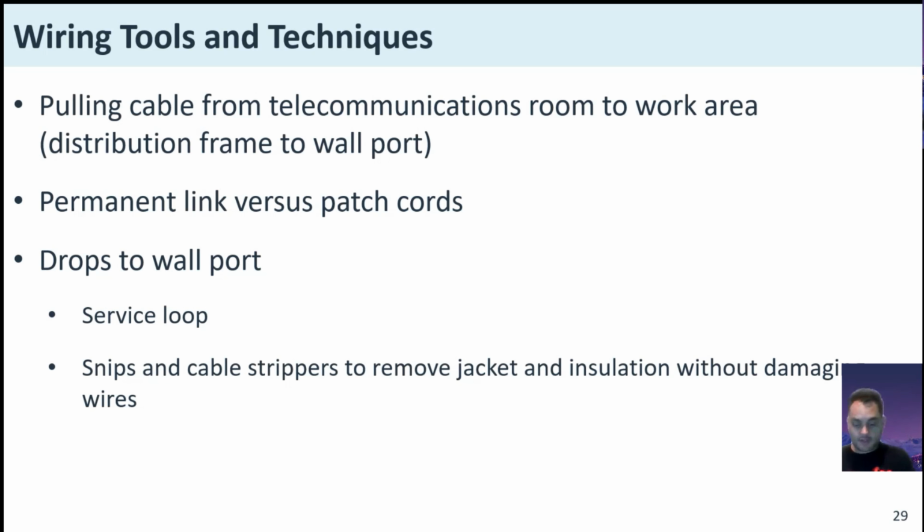That's also why in a lot of situations, like I was talking about with Nevada, Colorado, and a couple other states, you have to actually run conduit. You run the conduit and you run the wire through the conduit. If it's low level voltage, you run that conduit only for that wire. And if you have something that's high voltage, you run it in a separate conduit, ensuring that you don't have interference and that the conduit shields everything that it needs to.